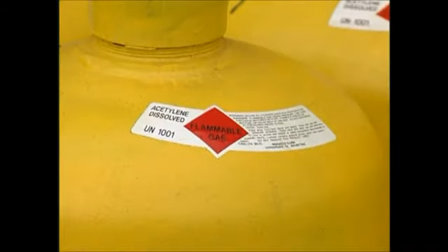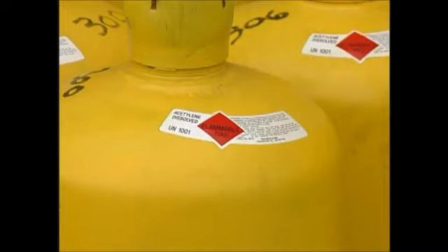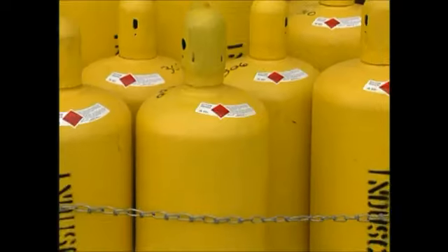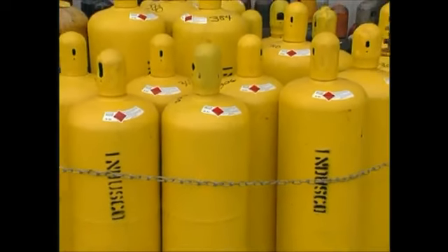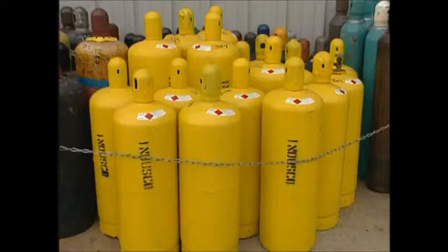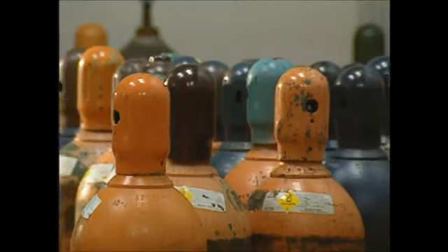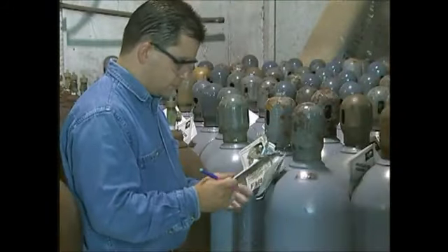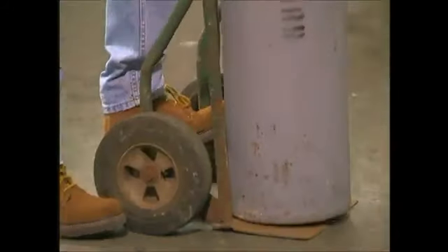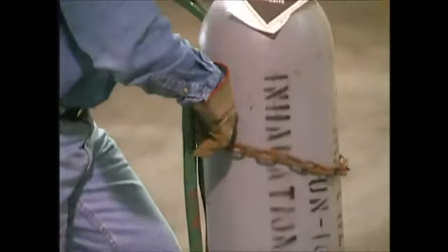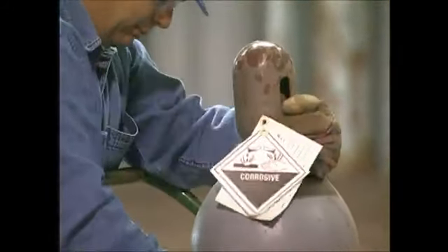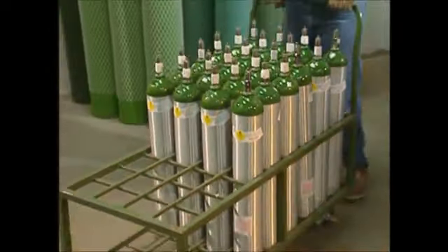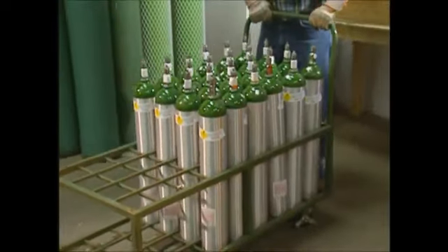Treat cylinders containing compressed gases as potential explosives. Don't expose cylinders to high temperatures. Excessive temperatures can trigger rupture prevention devices or cause explosions. When a cylinder is empty, promptly remove the regulator and replace it with a protective cap and mark the cylinder as empty. When moving or storing cylinders, secure them with straps or chains, or place them in an appropriate stand to prevent them from falling. Never use a cylinder that cannot be identified.